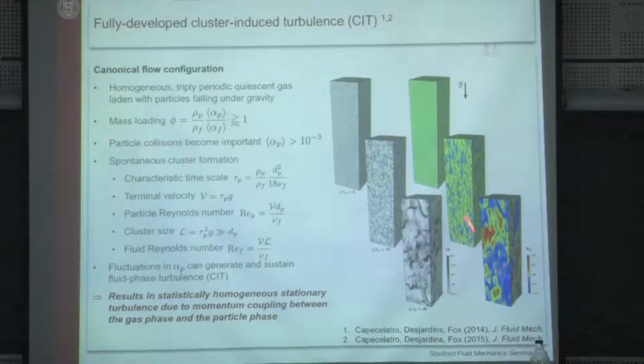And as a consequence, the flow field is also evolving. It's going from basically being equal to 0 initially to this complex, chaotic, fully three-dimensional velocity field. Why is that? Well, because the particles in dense regions, as they fall, entrain the fluid. But since we're forcing the fluid to maintain a 0 flow rate overall, the fluid has to rise in regions where particles are not entraining it down.